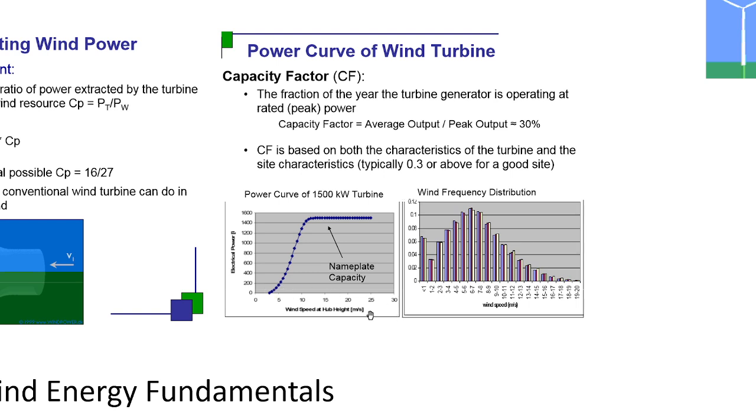at this wind speed bin, plus 4 to 5 wind speed bin about 400 kilowatt hour, at 6 to 7 it's about 5000 kilowatt hour. Beyond that, like this, you pick up the power from this and the number of hours of operation in that power. Ultimately energy is power into time, right? Yes, sir. Kilowatt hour. So you have to convert this power curve along with the probability of occurrence of that